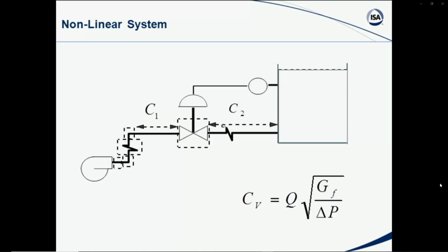If we take this a little bit further, though, and we look at how the valve is going to be installed, it will not be installed like it was on the test loop. It will not be installed like it was in the lab. It will have various other characteristics and attributes to take care of. The pump, there's a pump curve, of course, as you back up and down on the pump curve with respect to the discharge pressure and the flow rate.